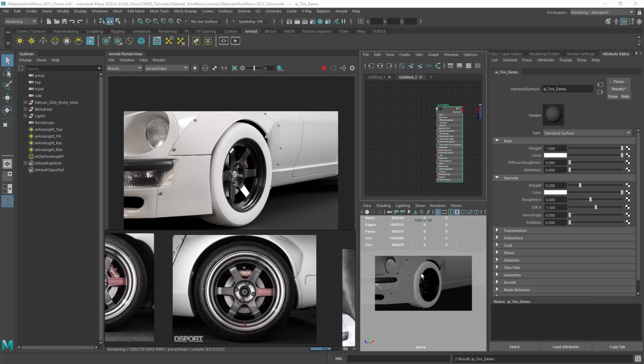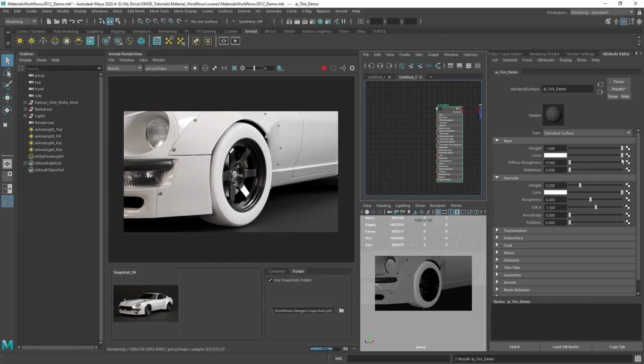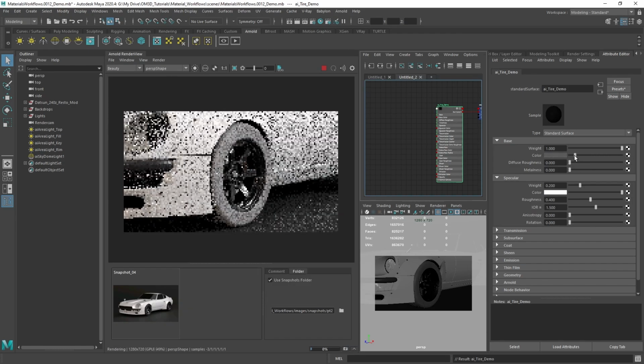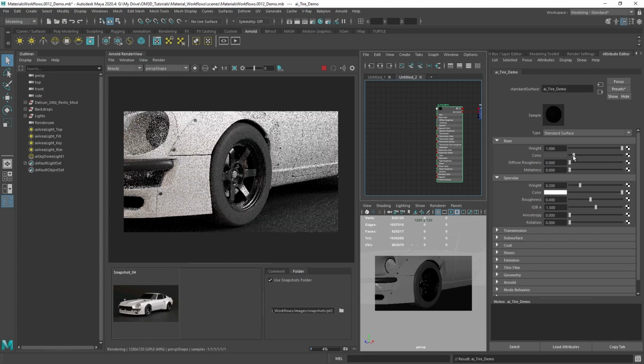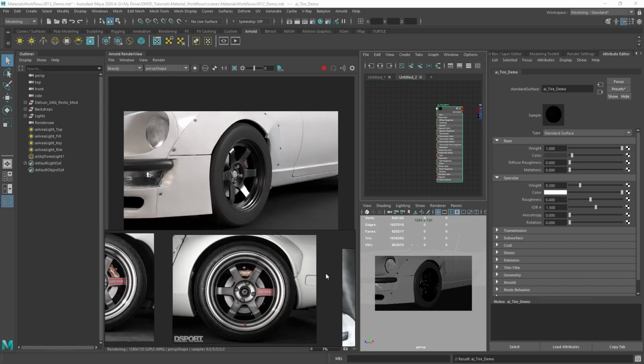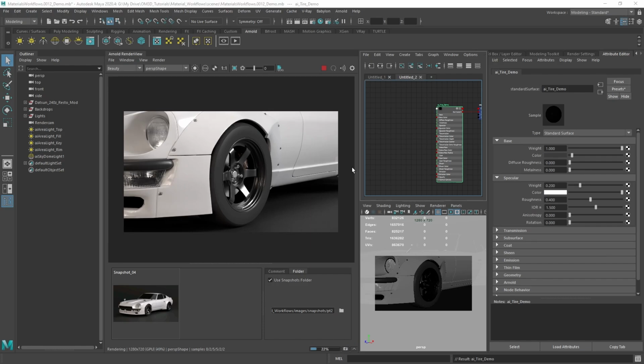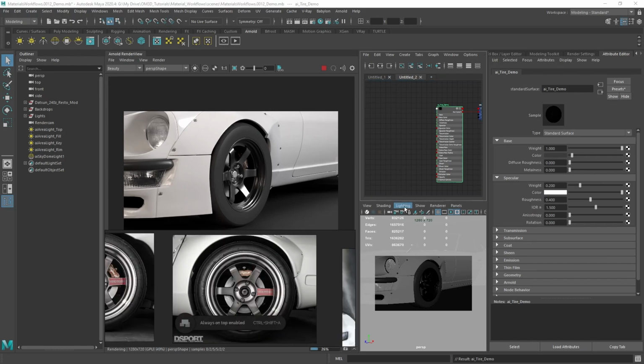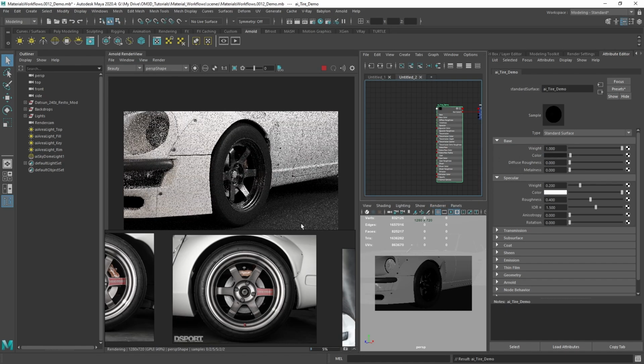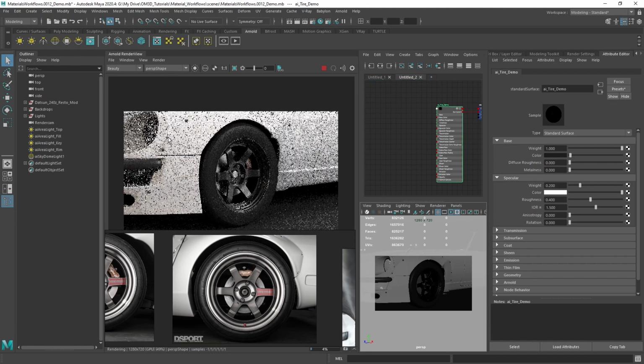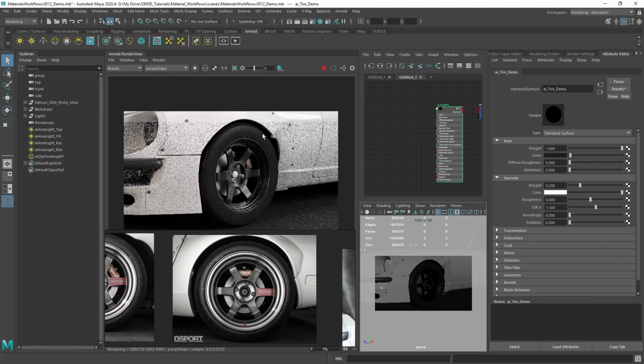With this in mind, I can select the material, and I can now set this to a little bit darker. I'm going to have this be actually pretty dark here. We're going to keep our reference up. If you're using PureRef, you can hit Control-Shift-A, and that'll make sure that it always stays docked. Whenever you don't need it, just hit Control-Shift-A again, and then it'll go away. So I can Alt-Tab, bring that back, Control-Shift-A, and there we go. I'm going to bring this really pretty dark here, get pretty close to what we're seeing. I'm using a similar light setup, so we should be pretty close in value and whatnot.